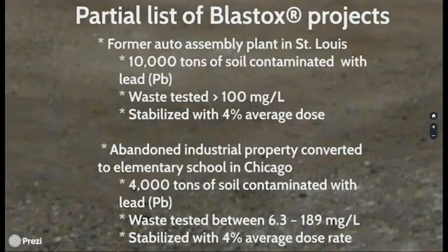And then they generally just had a burn pile area where, this predates EPA and the existence of a lot of waste management regulations, so as a result, it was very common to put them all in one large hole in the ground or a trench and burn them. Well, that's what happened here. But as that property became potentially more valuable, with real estate in the area going up in value, they decided to clean up the area. They did testing to determine that lead leached at greater than 100 milligrams per liter. At that high rate, we tested it and did a treatability study and determined that 4% of our standard Blastox 215 was quite effective.